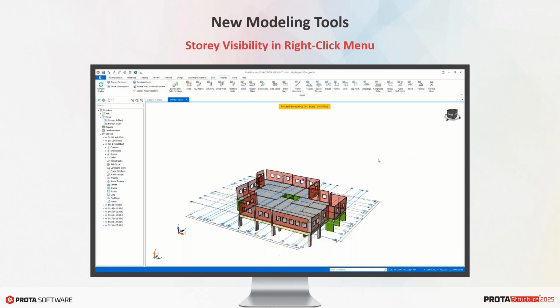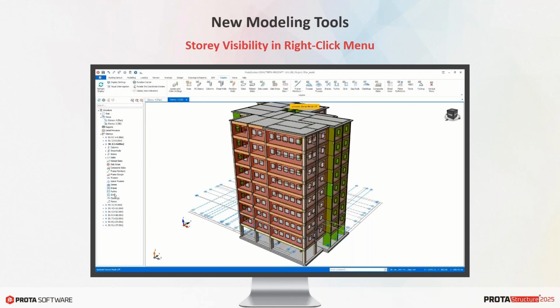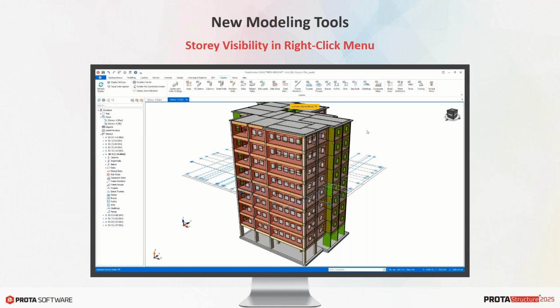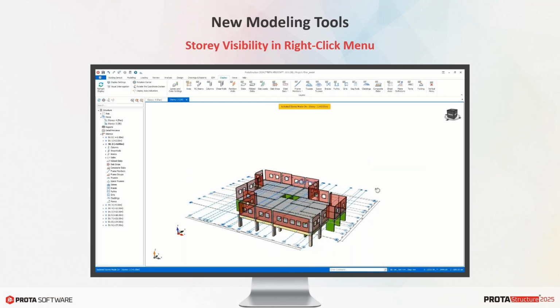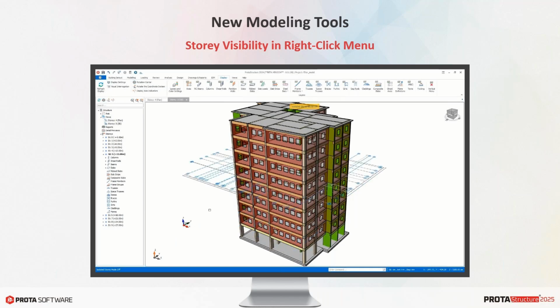3D view is very essential as it helps us to visualize and manipulate the whole model in 3D. But there are some cases where you may want to isolate a story and walk through it without the distraction of all the elements in the rest of the model. For such cases, you can now use the isolate and unisolate story option in the right-click menu. You can also use Ctrl plus left or right keys to isolate and unisolate the current story. Also, in isolated mode, you can use Ctrl up and down keys to change the stories.